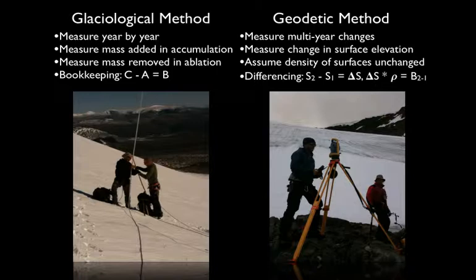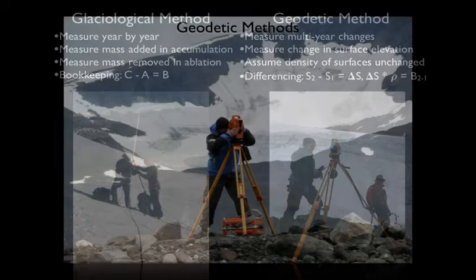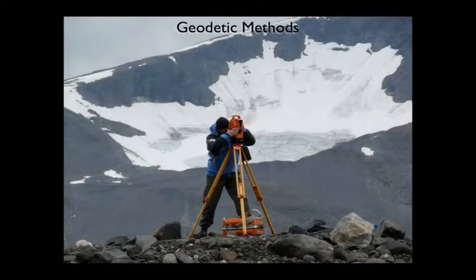The glaciological method requires measurement each mass balance year and can be compared with accountancy. Sum the net gains and the net losses to obtain a balance for the year. The geodetic method measures the volume of the difference between the glacier surface at 1 year and a subsequent year. The geodetic method requires a topographic survey of the surface to be performed at intervals that guarantee the survey errors are not larger than the change being measured.